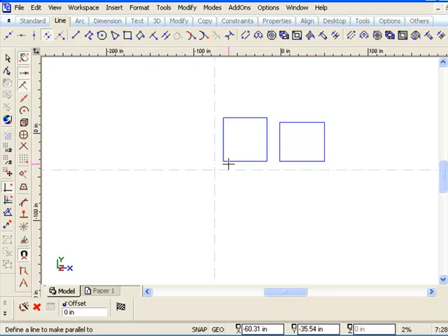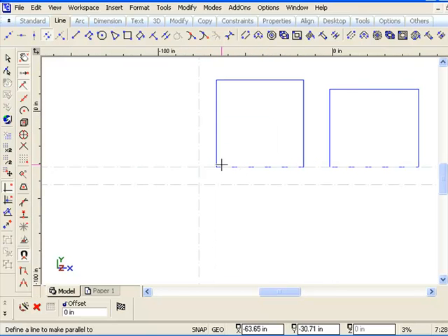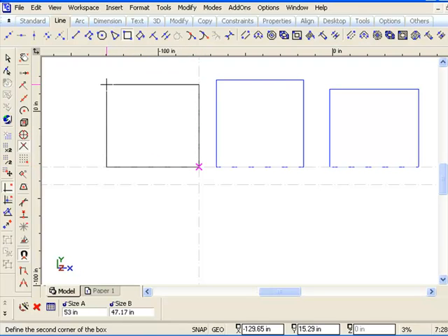Maybe I didn't want to go away from this. So I'll click there and now I'll just use the V key over there to define where that line is. So that parallel line now goes straight through there, right? Gotcha. And now what I can do is draw a line or a rectangle starting from this point. And for that one, I'm not going to use vertex. I'm going to use intersection. Now I can snap to that intersection, and then I can go and draw a line.